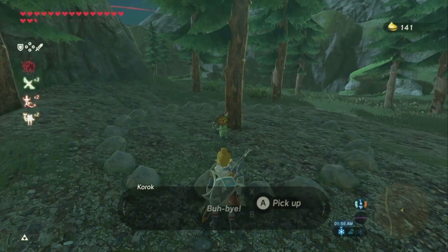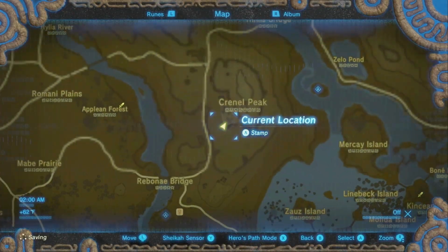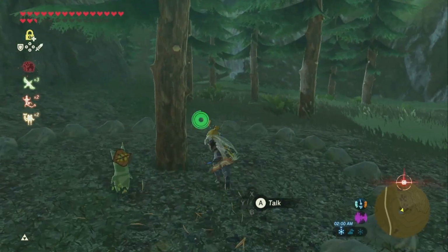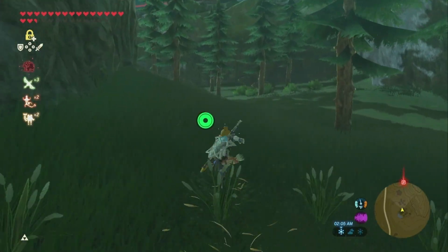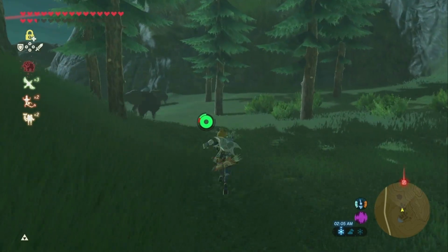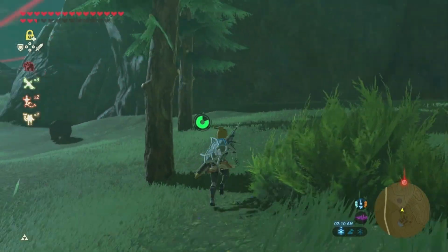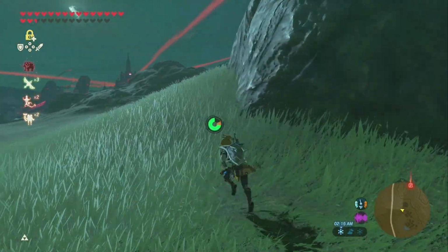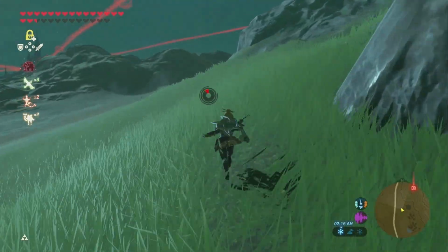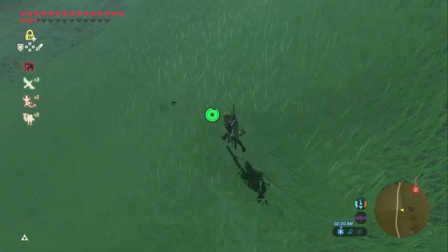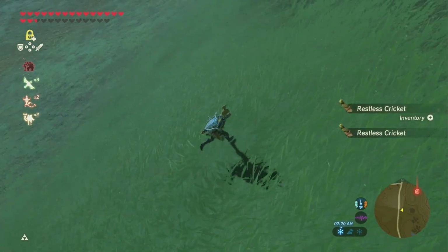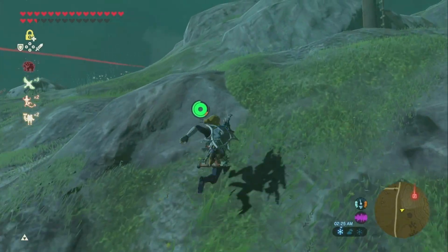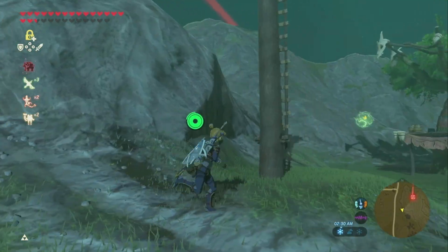Watch for PEX tubing. A controversial topic is whether PEX tubing can be connected directly to a water heater. The answer is yes and no. Some manufacturers, including Zurn, Z-U-R-N, say their PEX tubing can be connected directly to a water heater.